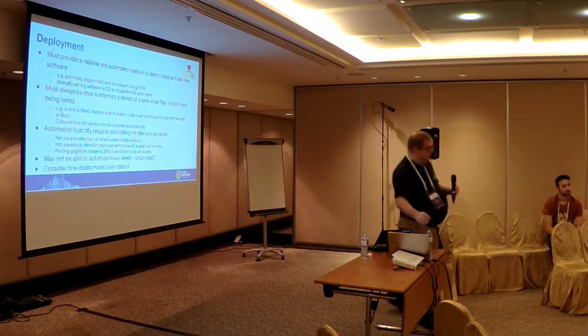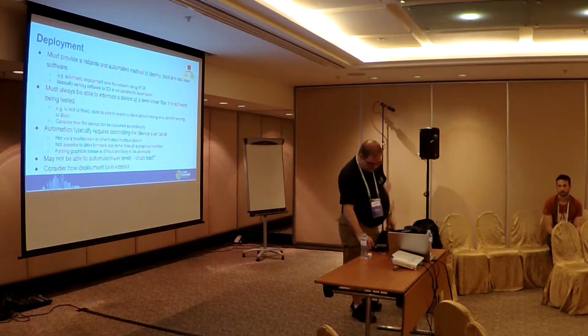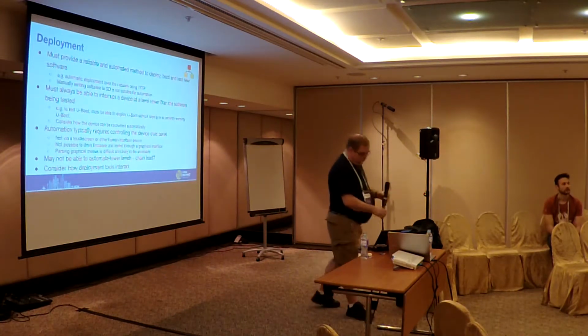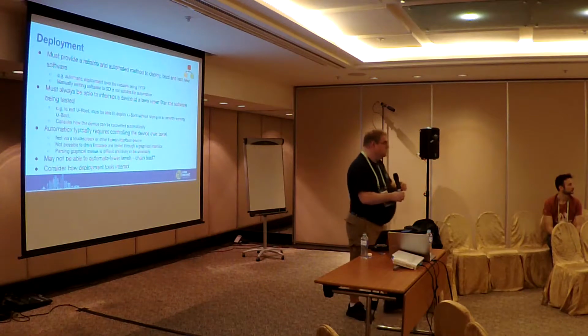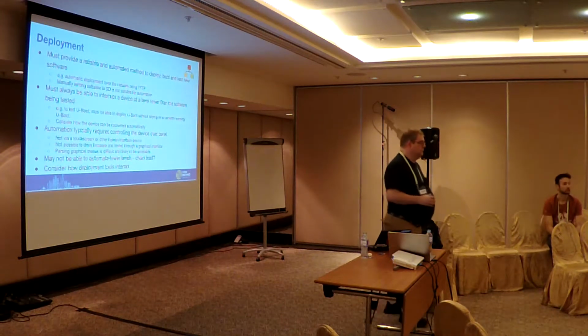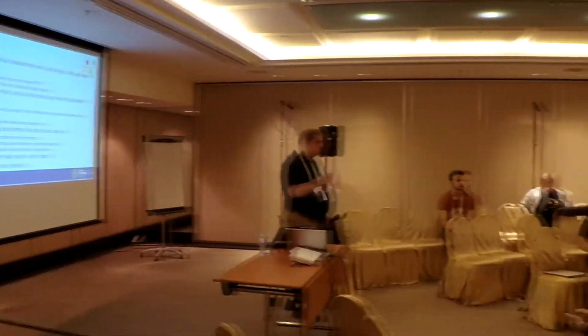Yeah, just on that point. What I was saying, where 9 times out of 10 I get into recovery mode, and 1 time out of 10 it doesn't. That is also true if you just put a jumper across it, by the way. You have to reboot and it will eventually come back into recovery mode. But when you're just doing that on your desktop and it doesn't show up, you go, I'll just reboot the board, and it comes back. In an automated environment, it doesn't work.